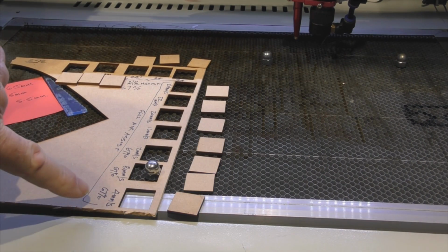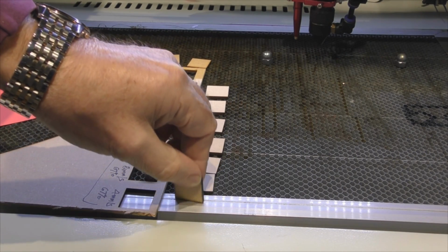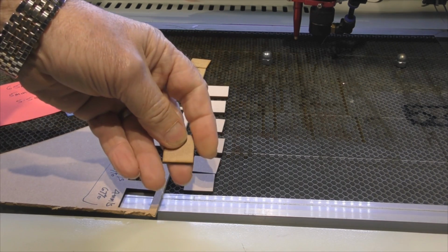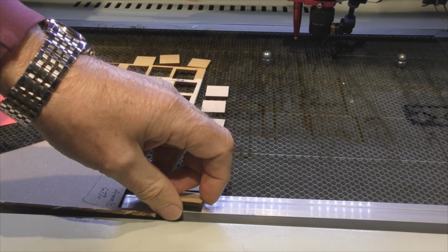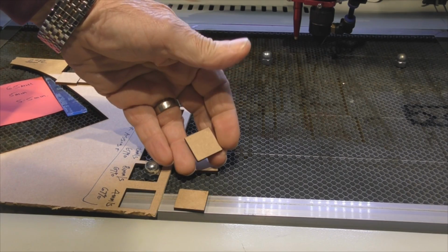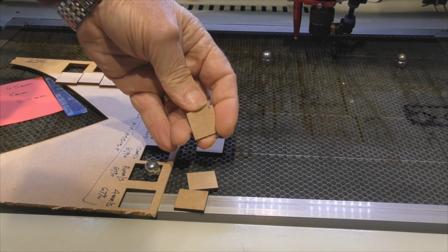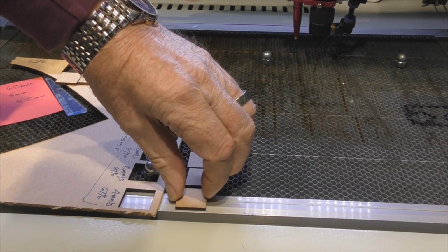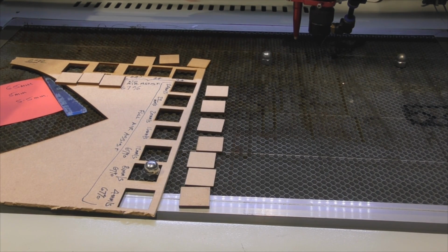This was the first one that we did very, very slowly. And one thing I'd like you to note on this one is how burnt the bottom edge is. Can you see how charred and brown that bottom edge is? Once we started getting a little bit faster, we get lovely clean bottom edges. So there's some other factor that tells you whether or not you're going fast enough or whether you're going too slow, and that's whether you're getting smoking on the bottom edge.